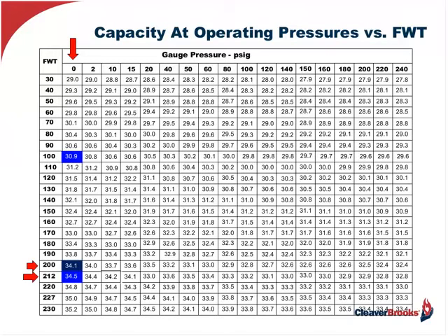If I were to drop that feed water temperature down to 100 degrees, we're looking at only 30.9, or 31, pounds of steam per hour, so I'm losing capacity. I'm losing horsepower because of the feed water temperature. So I've gone from 212 to 100 degrees. I've lost about 12% of my boiler horsepower because of that drop in feed water. Now, of course, I can make it up with my burner, but now that's more fuel.